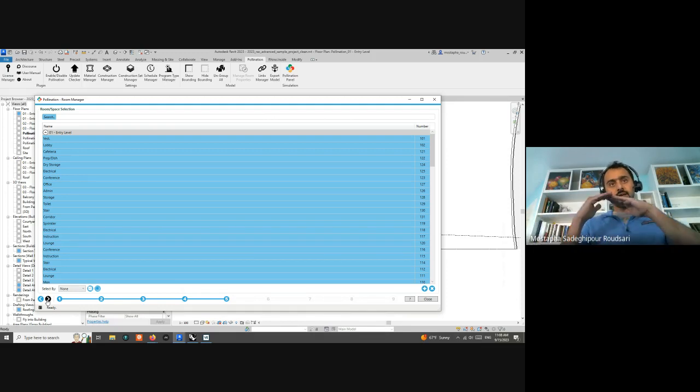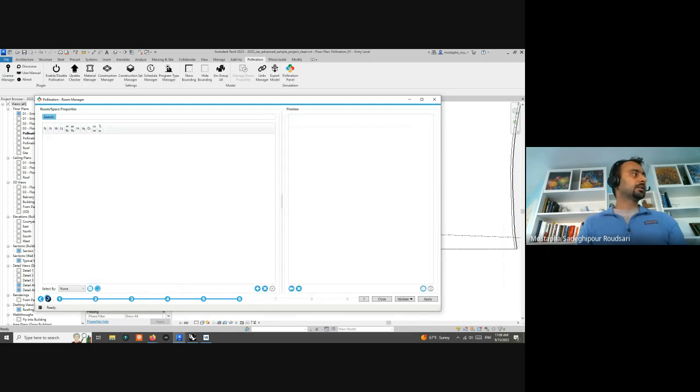So you can select a limited number of levels, and then from that level, you can also select only a few rooms if you want to run that, to just export those. The next step here is the place where the plugin really goes and parses all those geometries. So right now I'm exporting all three different levels together. Most likely, if you want to try with your model, you want to do one level at a time to make sure things are right before exporting them.